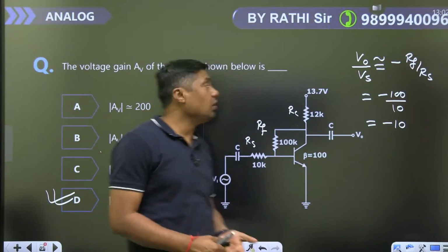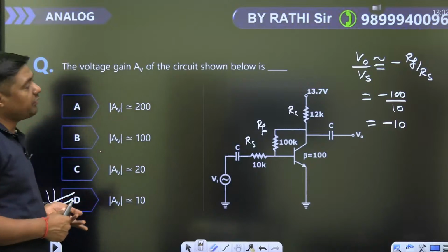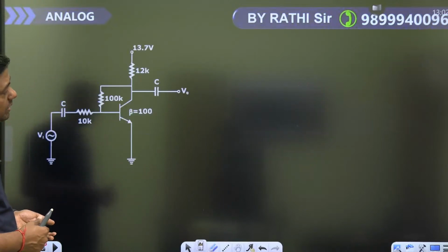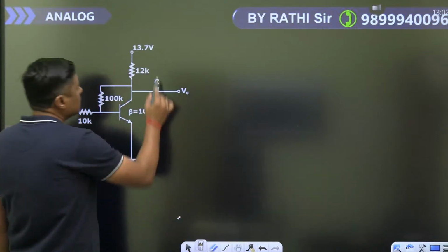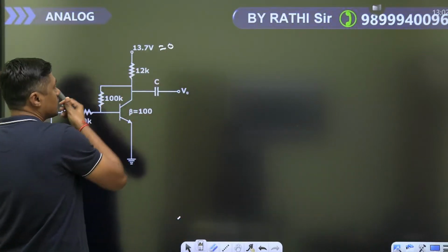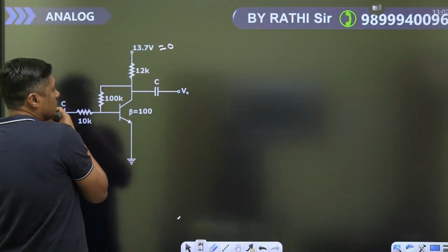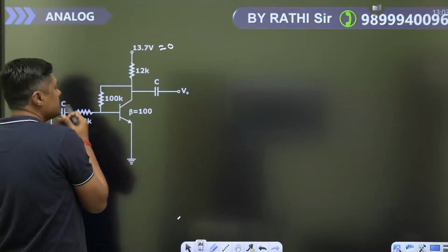But suppose you want to apply the model. Nothing is given. What is the beta? Very, very large. Base current negligible. Then how can we apply the model here? This will act as 0. Right? Then first of all, IC and IE are equal.